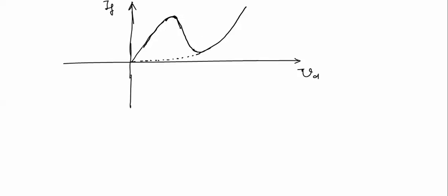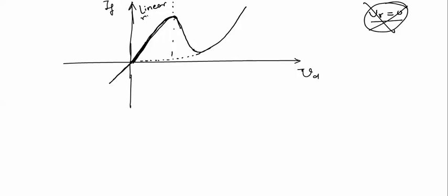These are the VI characteristics of a tunnel diode. As we can see, in this diode, if we apply a small positive voltage, unlike a normal PN junction, this diode is conducting. So we conclude that for this diode V gamma equals 0 volt, meaning there is no cut-in voltage for this tunnel diode. For small applied voltages, the current through the diode increases linearly with applied voltage. So we can say that it is operating in the linear region or ohmic region.